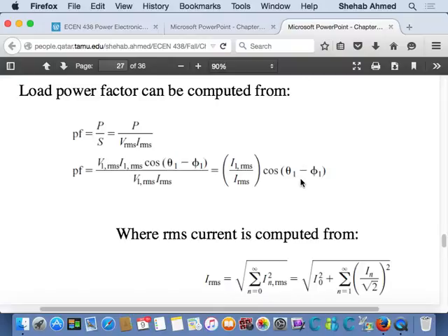But the energy meters that you have in your house are only calculating real power, the average real power being consumed by your house. So if you have an air conditioner and a computer and all these other electronic equipment and fans and motors, fridge motors, all of this stuff is contributing to a poor power factor, right?